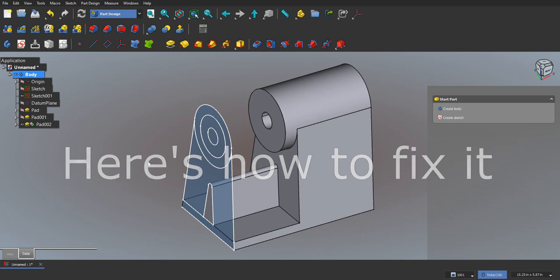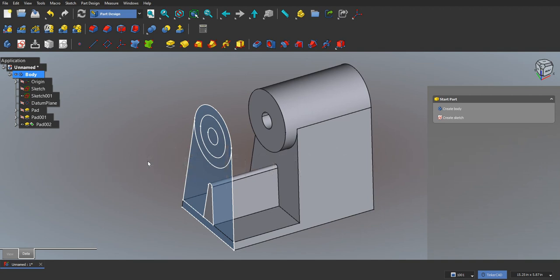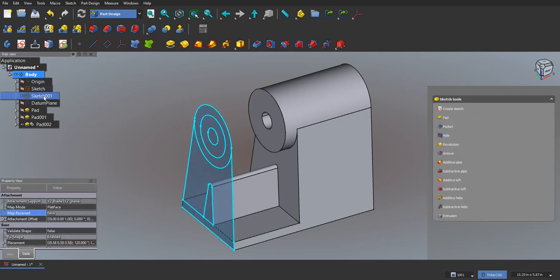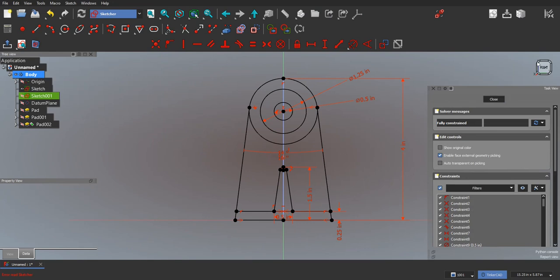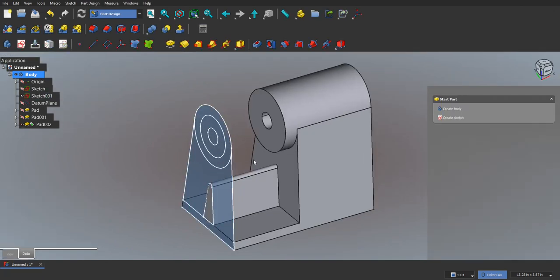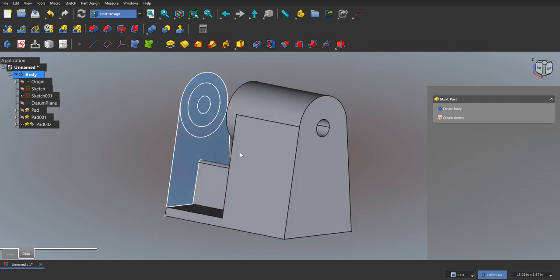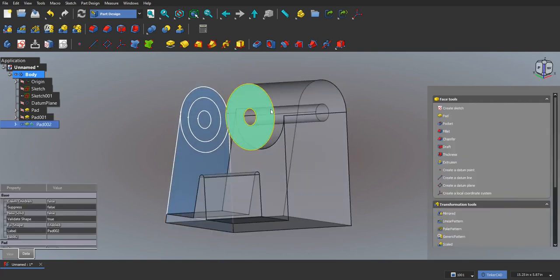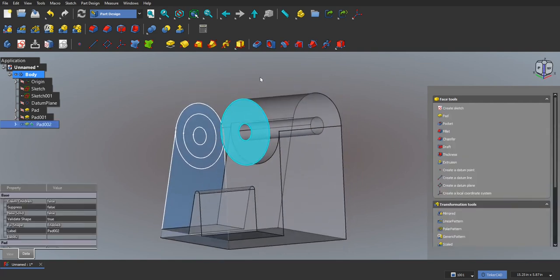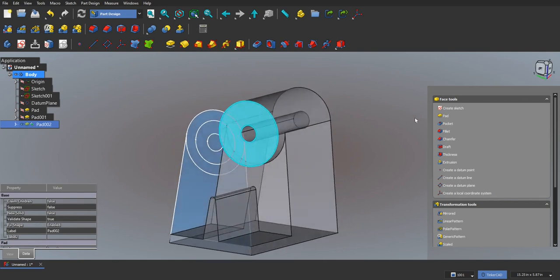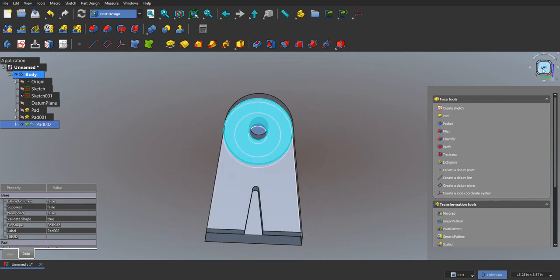Okay, so I went back and I messed around with it and I figured out why we were getting that issue. So when we made this first sketch, if I double click on this and edit, we are looking at the right view here. And so I'll close out of there. We were looking at this side over here. Now this face that we just tried to make the sketch on, once we look normal to that, we're looking on the left side.